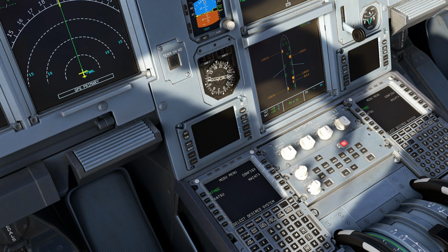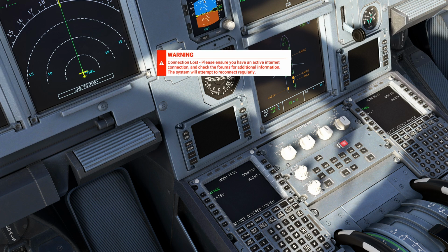And also we have a brightness control knob here that pilots can use to adjust the brightness of the lower display or system display unit. We have the EIS DMC switching selector, a switch located near the center of the switching panel, just above the ECAM control panel right here. It enables the flight crew to replace the captain or first officer display management computers.